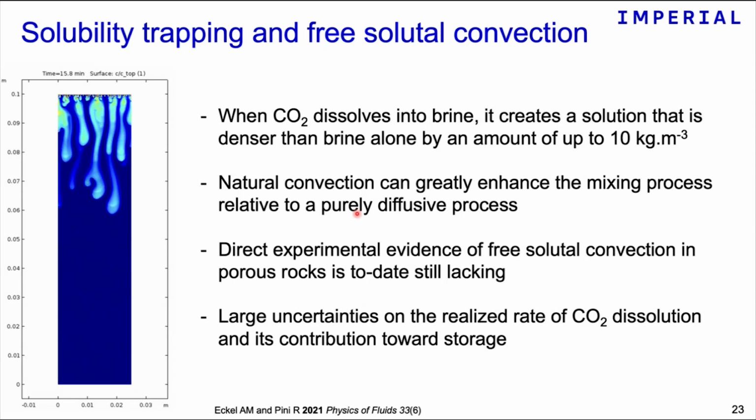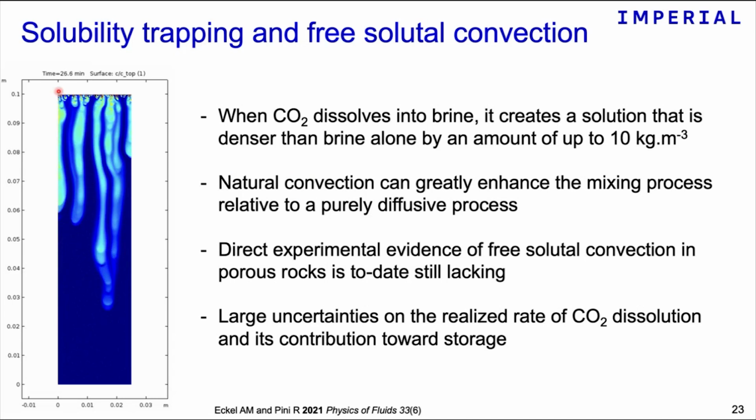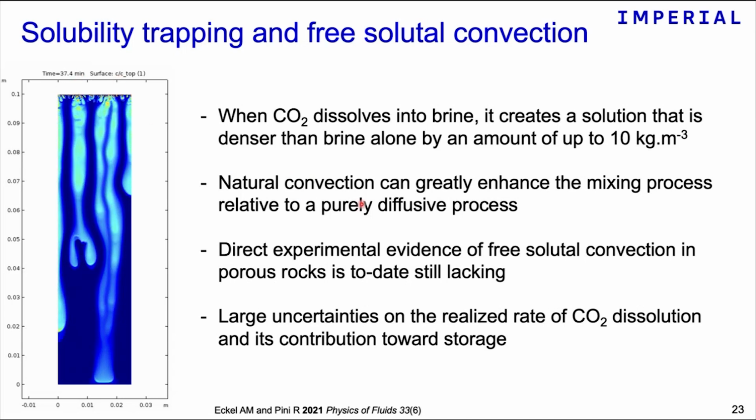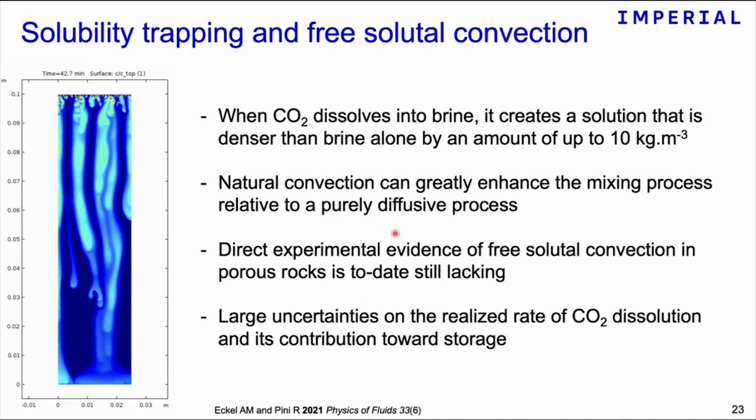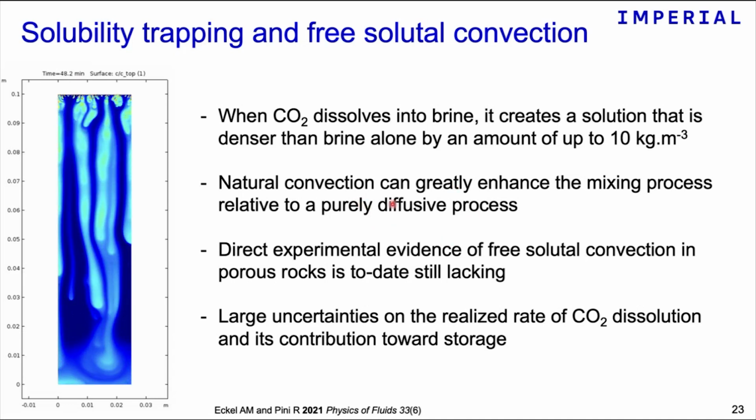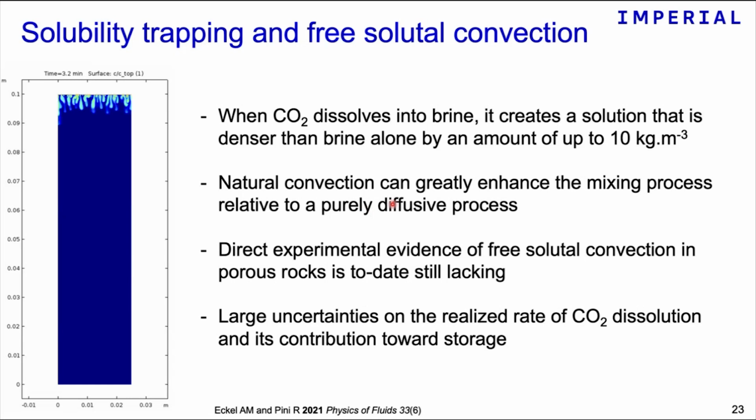But the important aspect is also that this convection will bring more fresh brine in contact with the main CO₂ plume, meaning that it can greatly enhance the dissolution, right? Because you keep feeding your system with fresh brine. There have been many studies providing evidence of this phenomenon, particularly numerical studies.